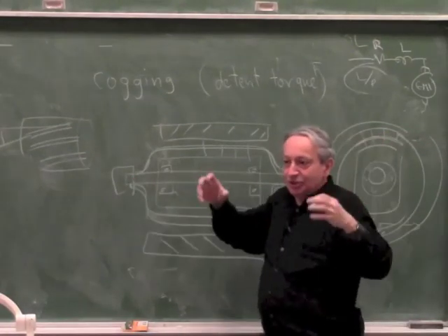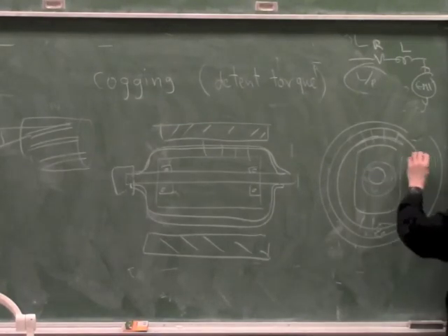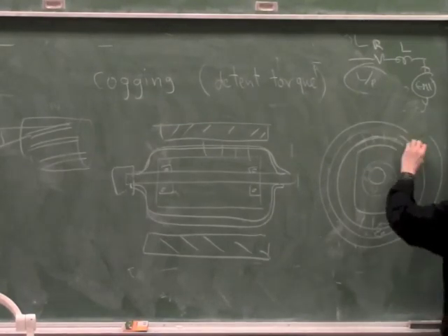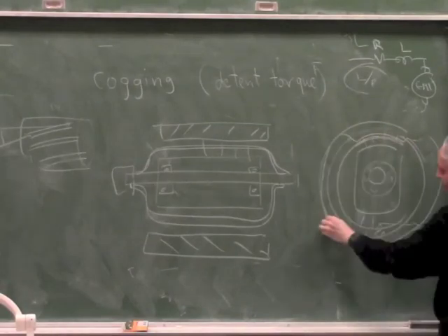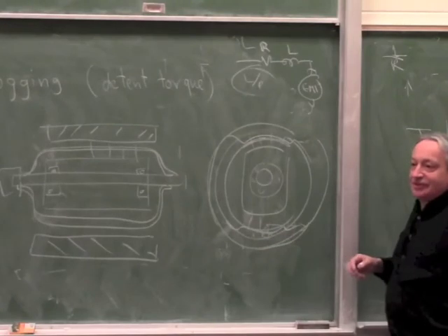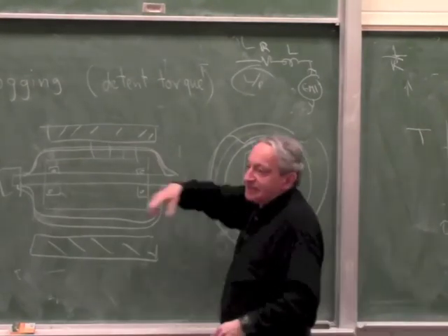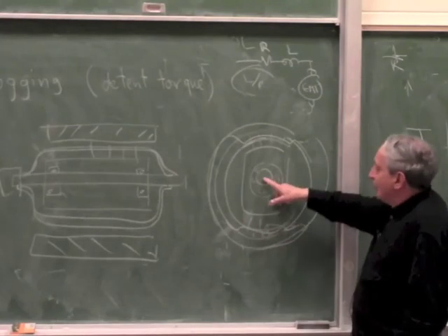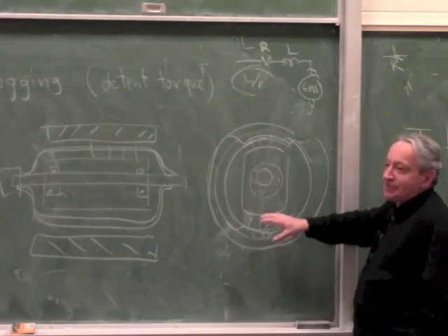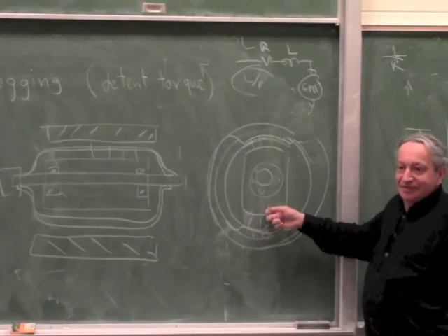So it can be much more rigid, and this can have salient poles. So basically this ring of steel can have salient poles to encourage the magnet to stay in one place. Now when you accelerate it, this hollow winding accelerates, but the shaft rotates, and the magnet stays in place. So you don't have to accelerate the mass of the magnet. Is that clear?